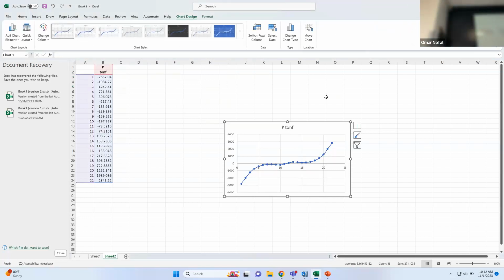And it's the same thing. You'll find that there's something going on here also because of the outrigger that you have. Okay. All right, so that's what I'm looking for to see. Okay, so I want to see these curves for all the models that you have. This is a very, very important phenomenon when we deal with full buildings. There are other structures like box bridges. They have the same phenomenon and you can plot it in a different way. But this is very, very important to understand what shear lag is and how you can get it. This is how we can get it.